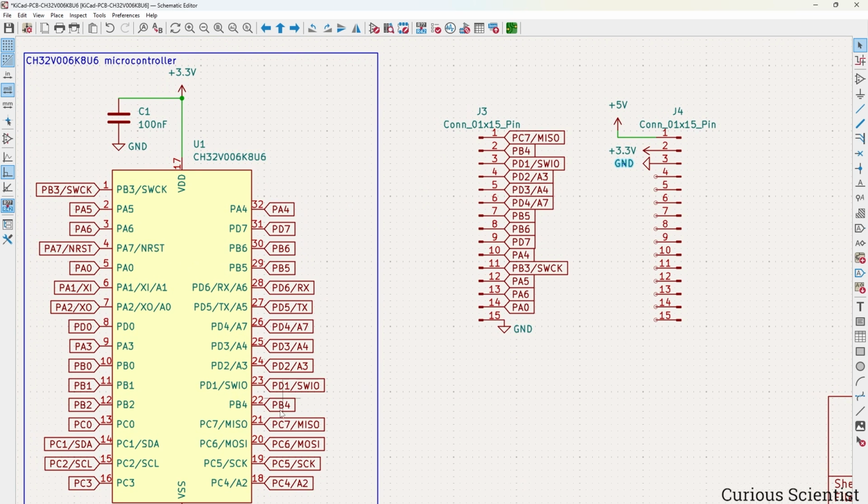Where we left off is, this is where we split the board into half, so you can see that the top here is at PC7, so now we have to go the other way, so PC6 will be here, and then PC5, and then we just continue. And this row is done, and you can see that after PD0, PA2 and PA1 would come, which are already used by the crystal. So if we would skip them and move to the next circuit, then PA0 would come, and that is already on the other side. So that's why I put the ground here.